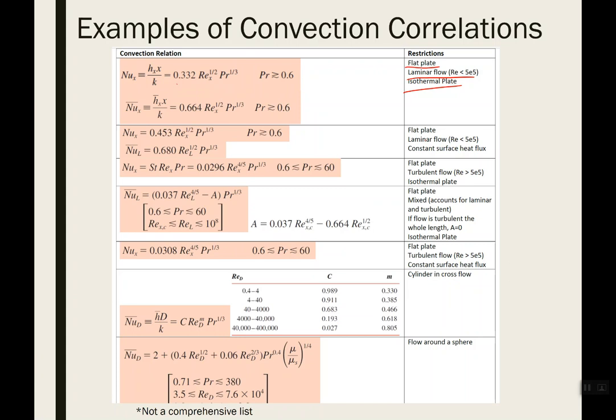One of the important concepts is that while we've treated convection as just sort of a constant so far, really the value of your convection coefficient can change depending on where you are on the solid. So that's where the local would come in handy. Often we may just make the assumption or the approximation that convection happens evenly, in which case we'd want to use the averages.